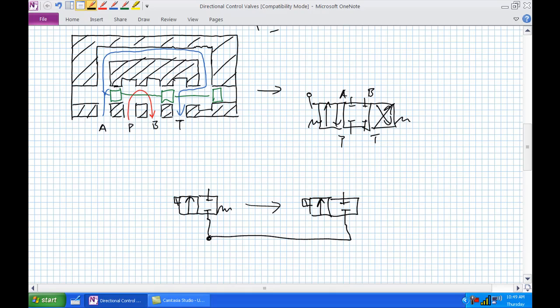And rather than duplicating a pump for each one of those things, you get a single pump that supplies all of them and associated relief valves. And whatever system A does, whatever system B is doing. So basically, that's an on or off button. So turn on system A, what it would do, the solenoid would push or pull that spool into its magnetic field and shift the spool into an on position, namely this one right here, okay?